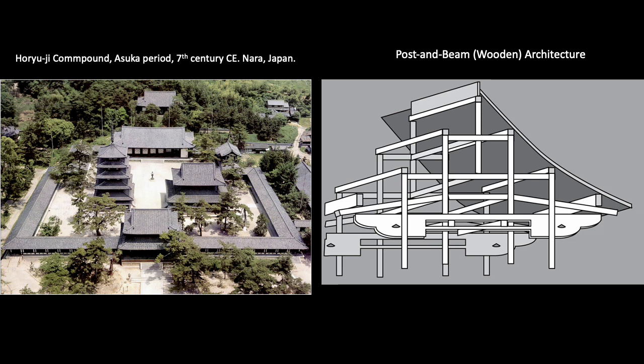This system consists of crossbeams and counterbeams, which create a series of layers supporting a very elaborate curved roof. Oftentimes, this curved roof seems to float because it's seated upon such slender supports. An intricate system of interlocking brackets crowns each column, helping to distribute the weight of the roof and large overhanging eaves evenly onto the wooden columns, allowing each one to bear up to 5 times more weight.